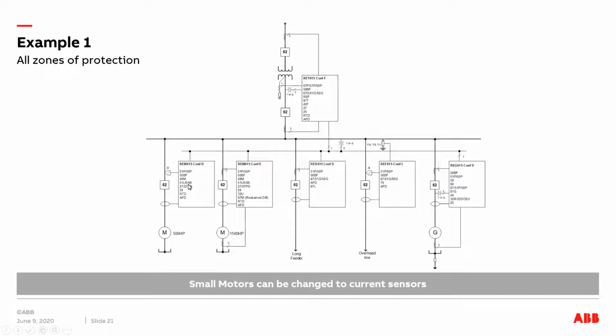And as you have noted, for the feeder, the configuration is changed to configuration L, because that is the configuration which accepts a current and voltage sensor input. So we change the configuration of the relay depending on the type of analog input it receives. Okay.